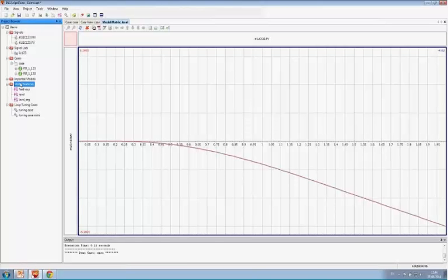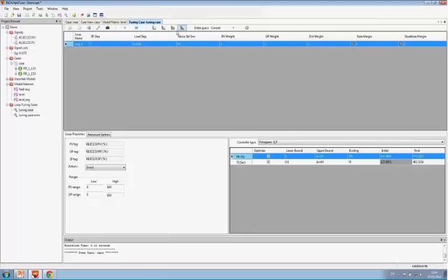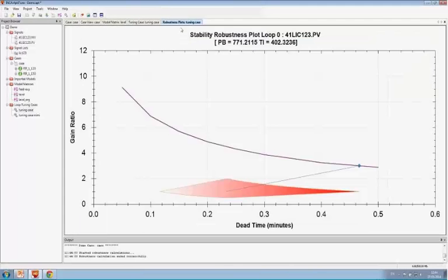One is you can use a transform to get a nicer linear model. Then you know what your transformation is, so what your fixed nonlinear behavior is, and what your linear model is. You can use this information in a robustness plot to say, okay, I'm stepping through a quite broad range, so I have to have a more robust controller dealing with gain changes. That's the main thing you can do, or you can use the transformation in a DCS if you have that possibility.